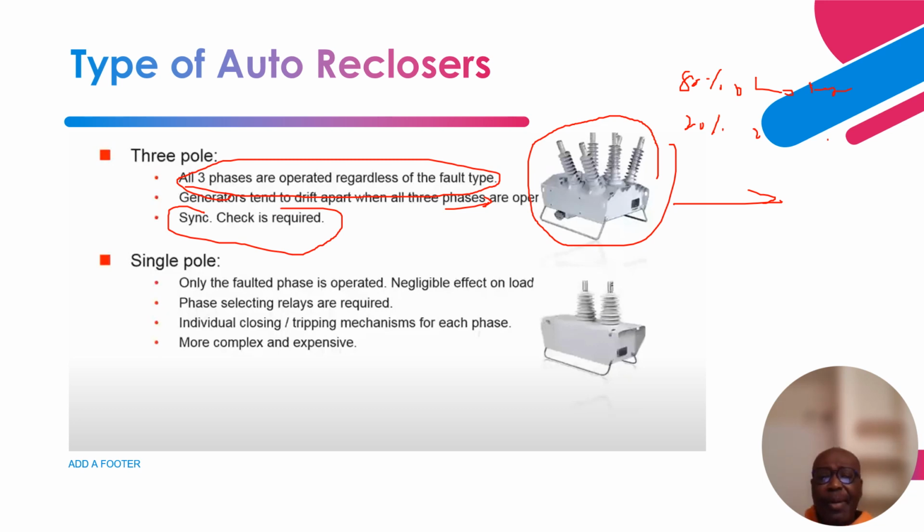So these are the typical set points, and the sync check relay, the 25, checks to make sure of that. Also there's a phase angle difference between incoming voltage and outgoing voltage. So it checks the voltage on this side to operate, and also the voltage on this side, if this voltage is coming from another source.